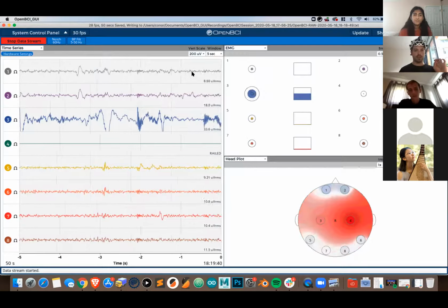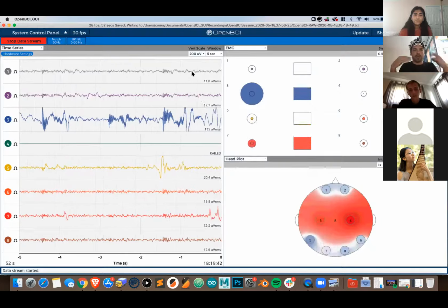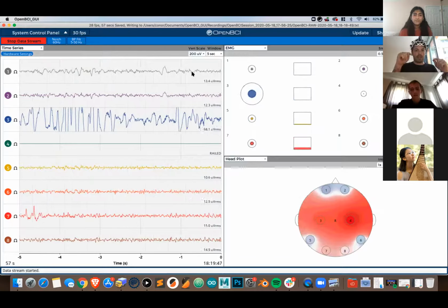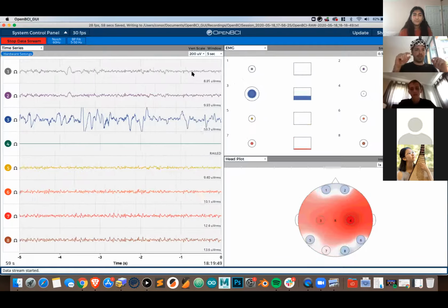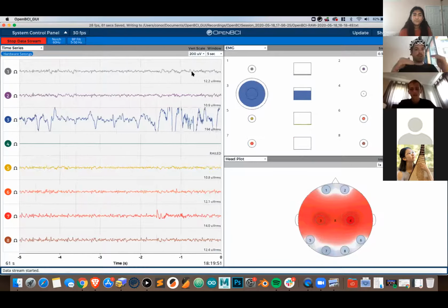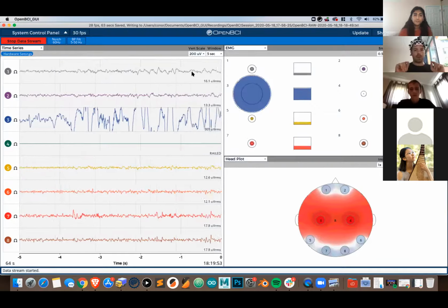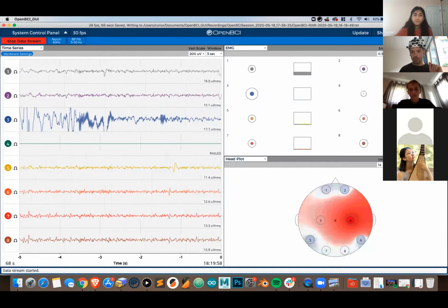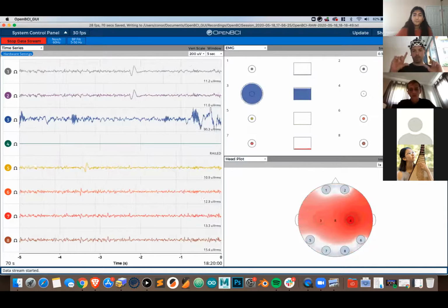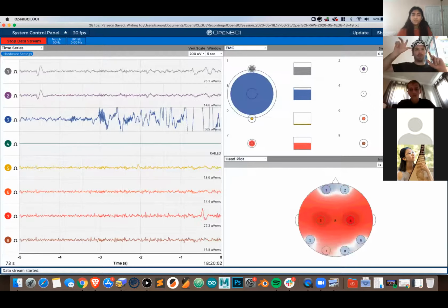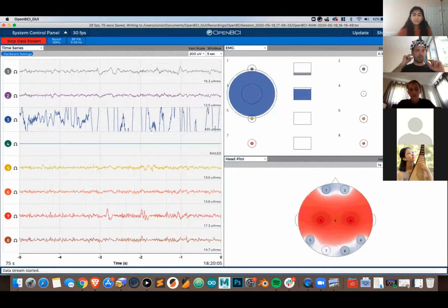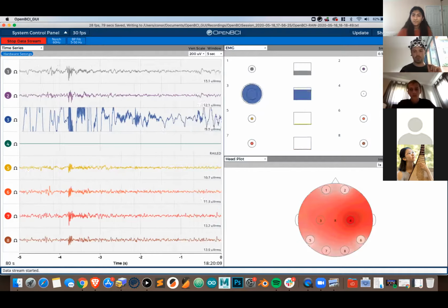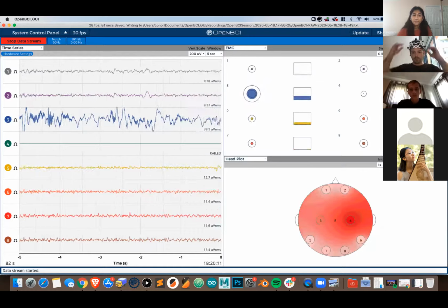So these little signals, these little electrical waves that are splashing out of my brain and onto my skull and against my scalp are oscillating, basically in the 1 to 100 microvolt range. So very, very small values. Here I want to look at just the amplitude, as opposed to plus minus polarity, because you can be plus or minus voltage in terms of reference to your bias. So I'm just going to switch this to a plus. It's kind of like the absolute value, basically.